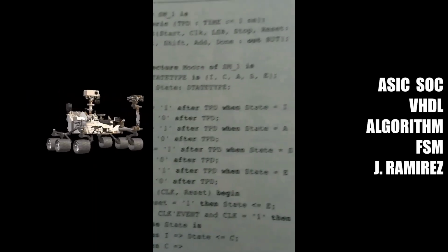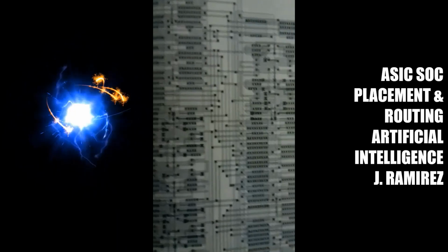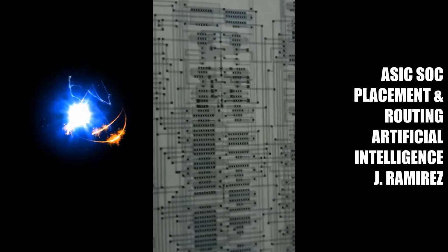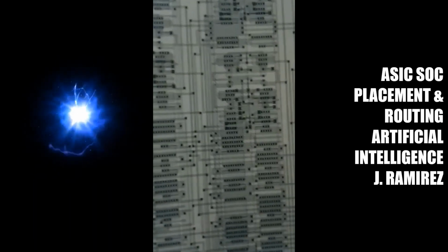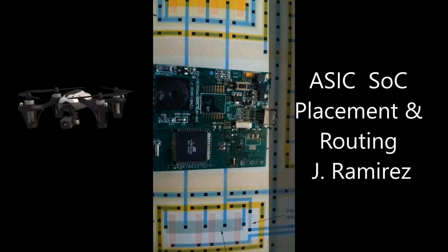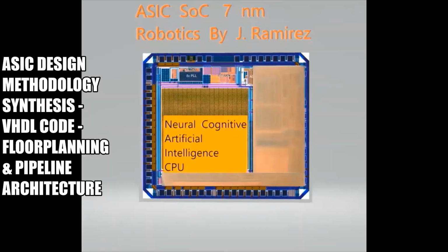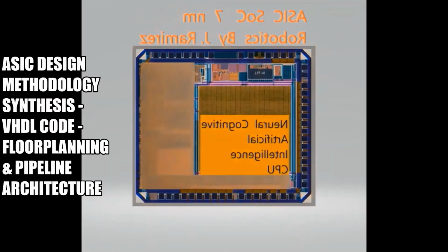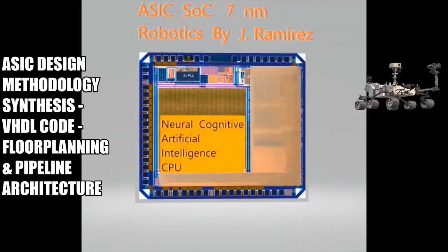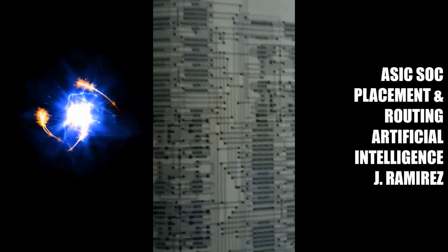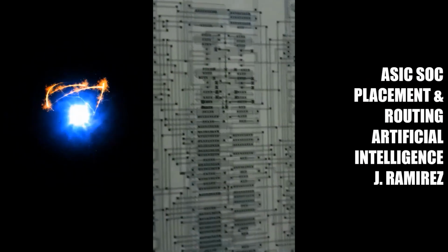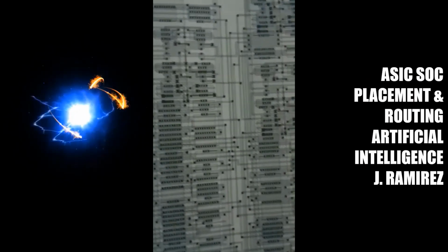Perform bottom-up timing abstraction generation. 3. Apply the top-down hierarchical timing closure methodology. If significant progress has not been made towards the timing closure, selectively flatten the problem blocks and either repartition them or leave them flat.